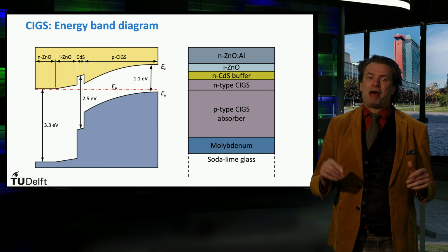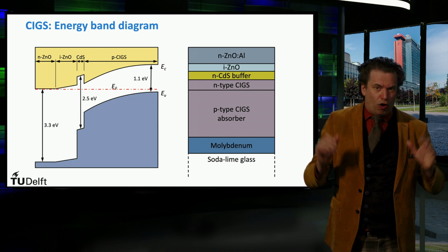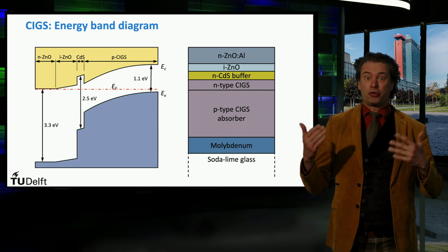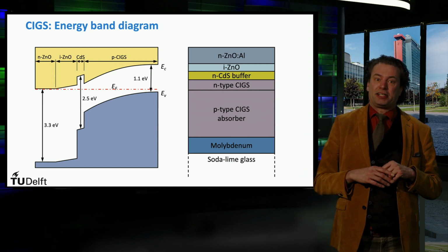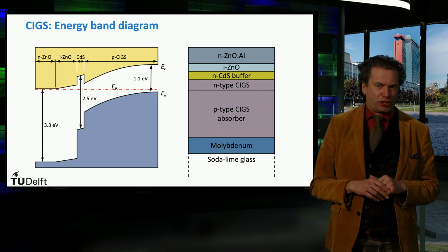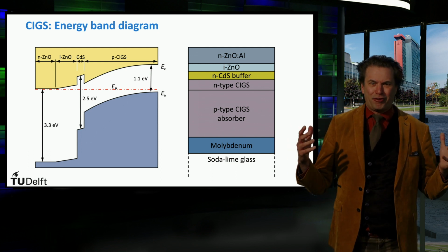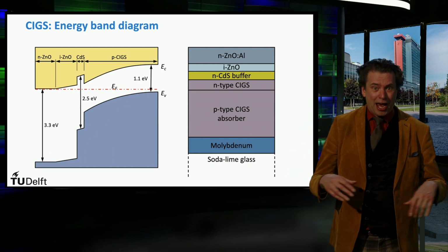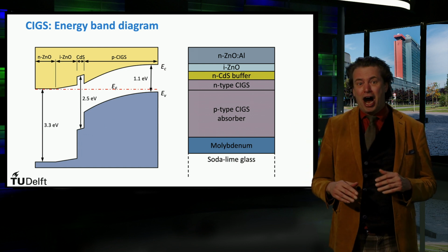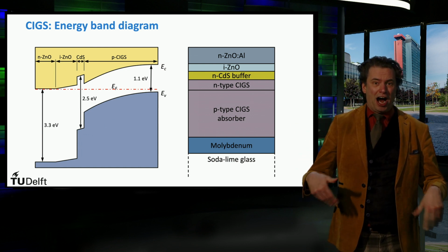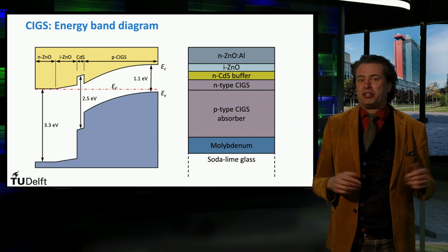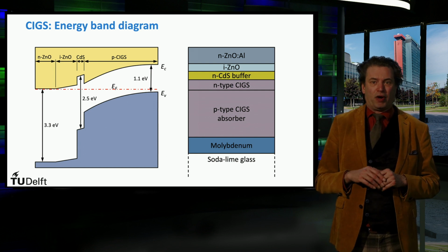One of the important aspects of the CIGS solar cells is the role of sodium. Low contaminations of sodium appear to increase the conductivity in p-type CIGS materials. It leads to a welcome texture and an increase in the average grain size. The larger the grain size, the fewer grain boundaries and less recombination are present in the material. This results in higher band gap utilization and higher open circuit voltages. Typical optimum concentration of sodium in the CIGS layers is 0.1%.